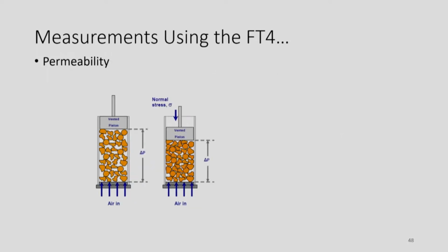So permeability, again, is how much passes through the solids, right? One advantage of this machine is that you can change the stress or pressure, so you can check the permeability or the pressure drop at different pressures, different stresses or different loads. That way you can simulate large scale bins. At different locations within the bin, you will see different stresses, pressures and loads. You can get that by changing the normal stress and finding the pressure drops, to see how much air will flow through the solids.